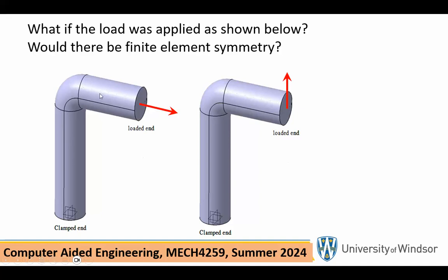Now remember, just cutting it in half is not the end of the story. That artificial surface that you have introduced by cutting this thing has to be put on a surface slider. The same thing here. If the load is upward, there is a plane of symmetry. But if the load is sideways or at an angle, there is no plane of symmetry, and you have to do the whole thing as I'm showing it to you.